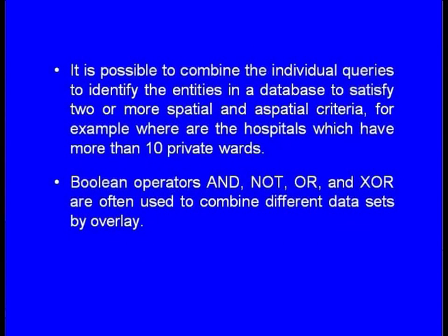It is possible to combine the individual queries to identify the entities in a database to satisfy 2 or more spatial and aspatial criteria. For example, where are the hospitals which have more than 10 private wards? In order to do this sort of analysis, Boolean operators such as and, not, or, nor are often used to combine different data sets by overlaying.